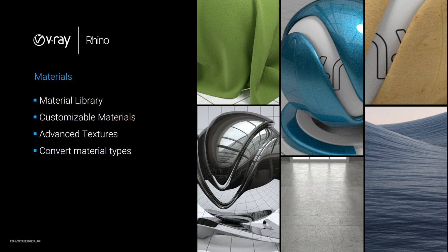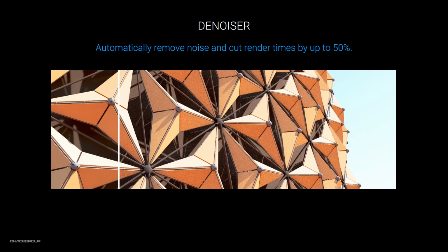Let's see another optimization using VRay. This is the VRay Denoiser. I'll show how the Denoiser can help us and cut the render time. The concept is to render the image in one stage, usually with lower quality, and then on the top have a post-process to denoise this image and get rid of the noise in our renderer. VRay Denoiser takes an existing render and applies a denoising operation to it, removing noise but keeping the details. It relies on other render elements and can't calculate during the render or after this.